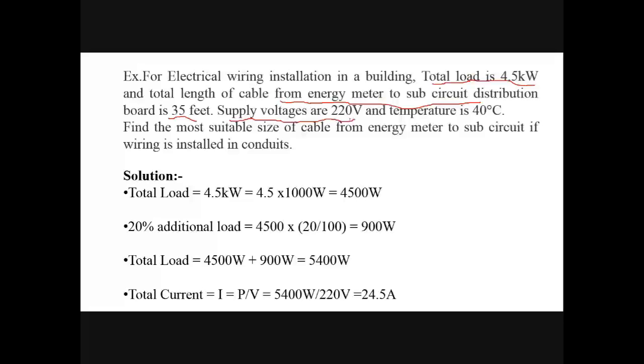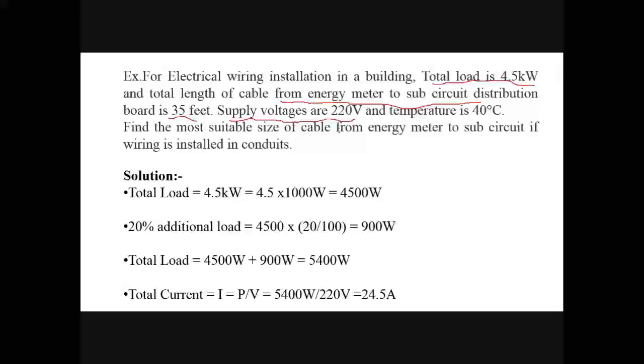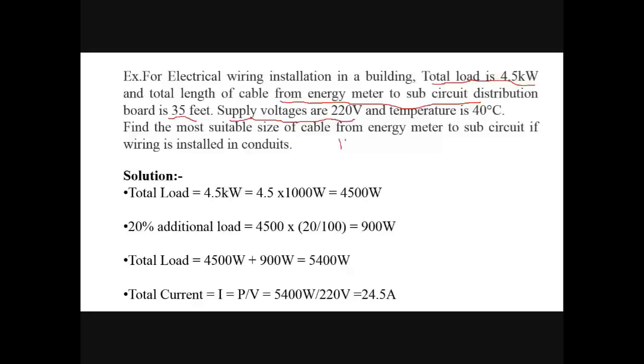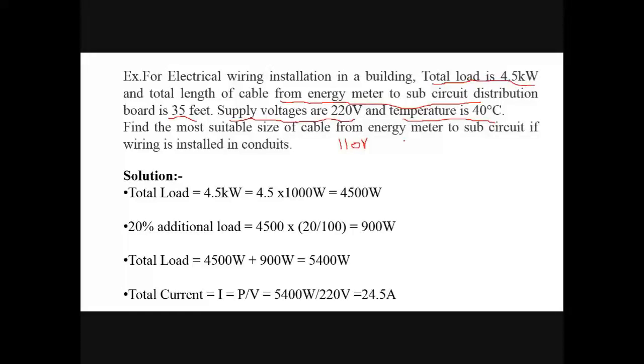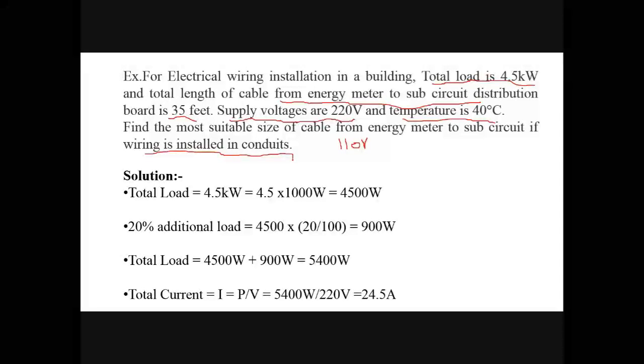Obviously, this is the case of India, and they have given the voltage as 220 volt. But if they give the voltage as 110 volt, it is not the case of India. It is the abroad case. Outside India, the supply voltage is 110 volt. And the temperature is 40 degrees Celsius. Find the most suitable size of cable from energy meter to sub-circuit if wiring is installed in conduits. Might be in your house, conduit wiring is already used.